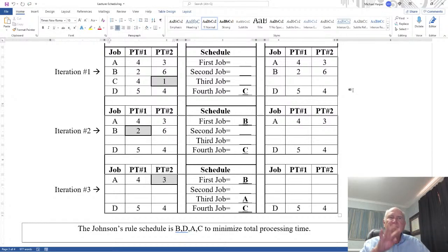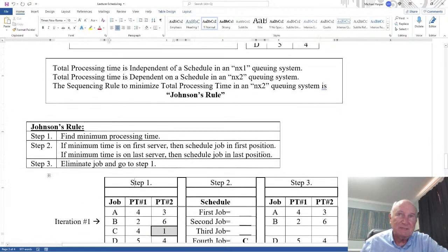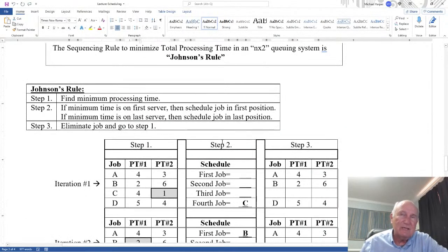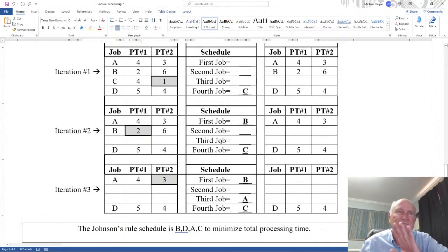Suppose you had 20 jobs on 4 machines. Well, you can say, I'm going to add the first 2, the last 2, do Johnson's rule. Or just do the first one and the fourth and do Johnson's rule. And then the middle 50% do the second and third machine server. So you can just use that concept even when you don't have a specific n/2 system. Okay, and it turns out it's not perfect, it's not optimal, but it's a very good system. It's a very good schedule.